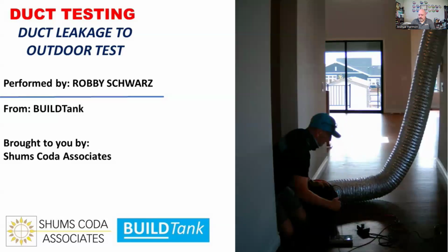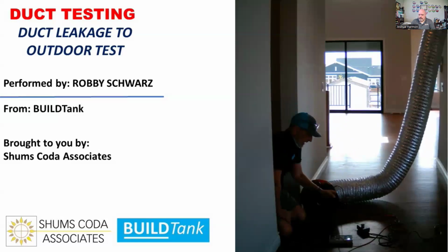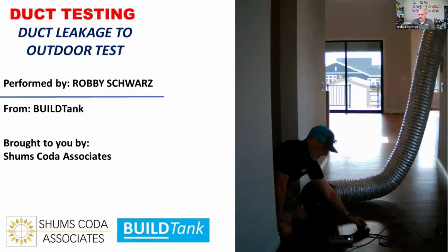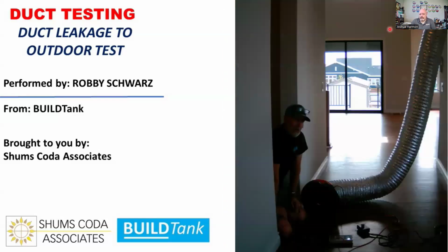So I'm turning on the fan, in essence, to chase the air from the blower door that's going through here and zero out that pressure. And once I've zeroed out that pressure, I've equalized the flow that is leaking out of the holes up in the attic duct system. So I have about 35 cubic feet of air that is leaking outside the building envelope.